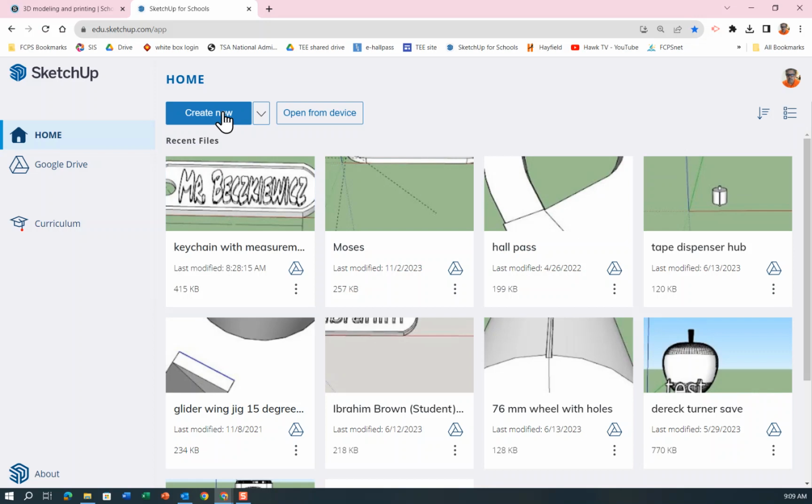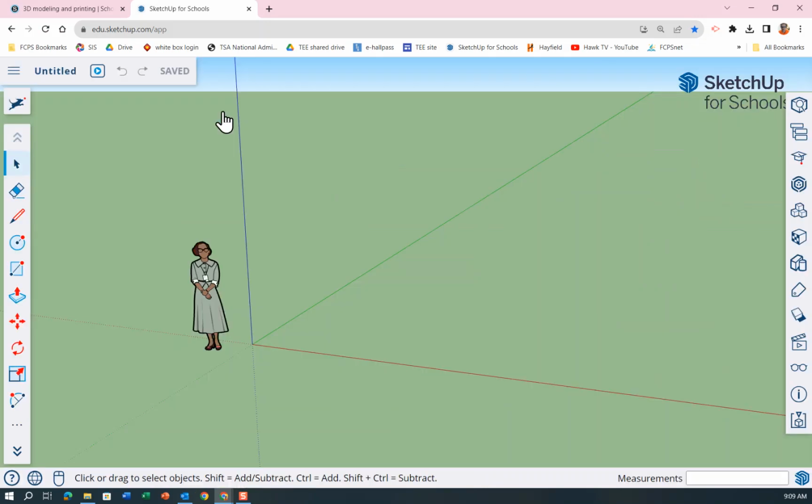Creating a new 3D model. You see I already have a bunch of stuff in there and it looks like this. So the first thing I need to do is a rectangle down here that is the size of my 3D printer bed. I click the rectangle on the menu, start at the origin, and start moving my mouse to make a rectangle. And remember, we want to make our rectangle 220 millimeters, comma, 220, enter. And it draws it for us automatically.